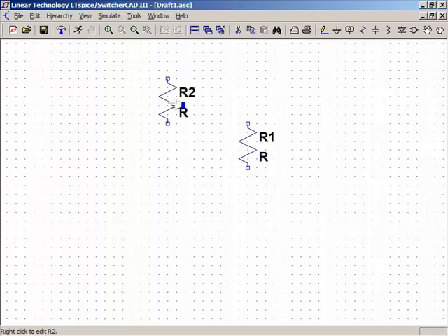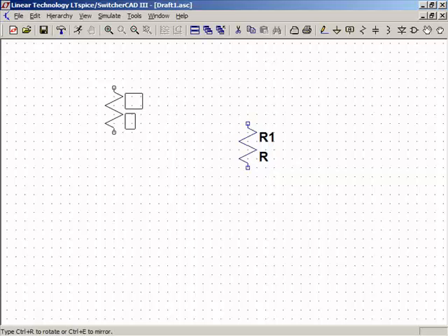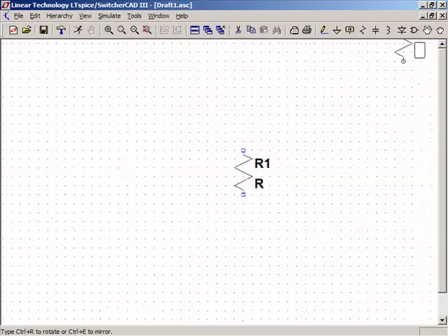Now I want to rotate this resistor, so I'm going to go over here. Now this is move, and this right here is drag. Now let's just click the move. We'll see what those do in a moment. So I've got this going, and I want to rotate it. I've got this on a low resolution screen, so there are actually additional icons we can't see over here.